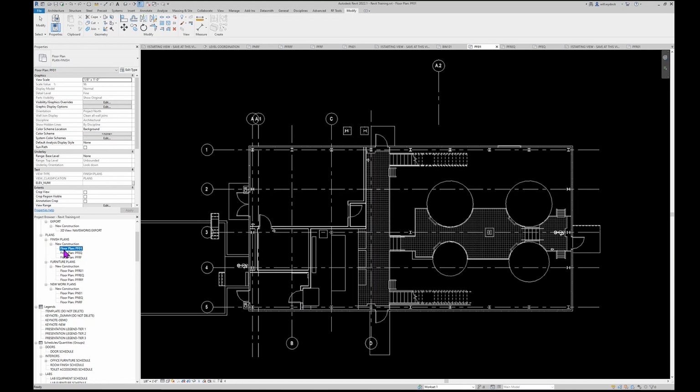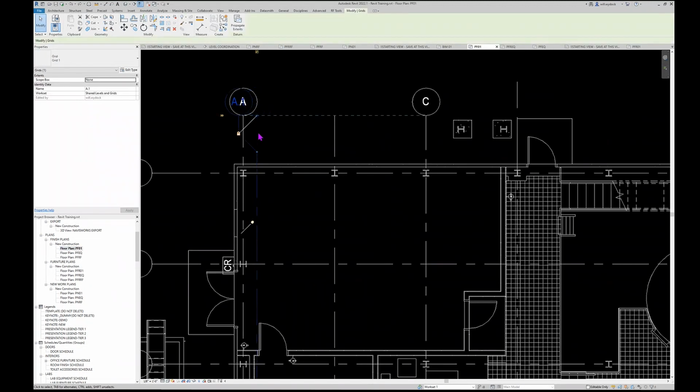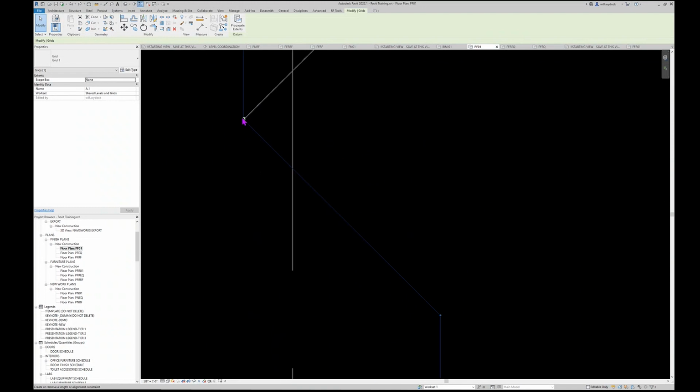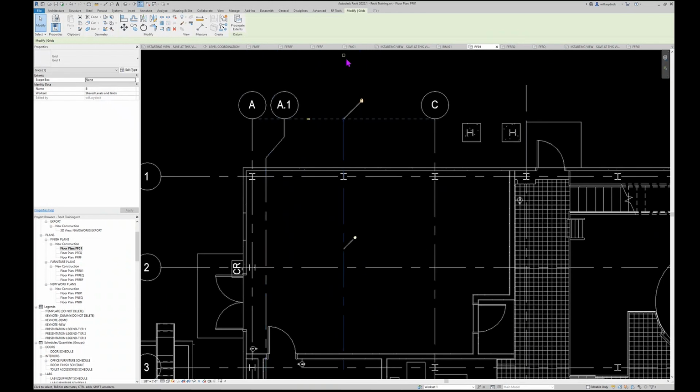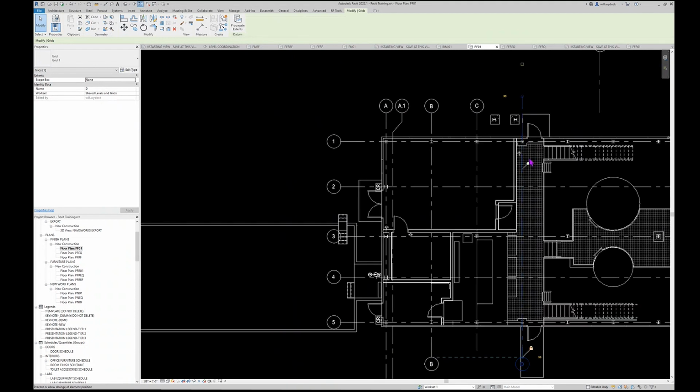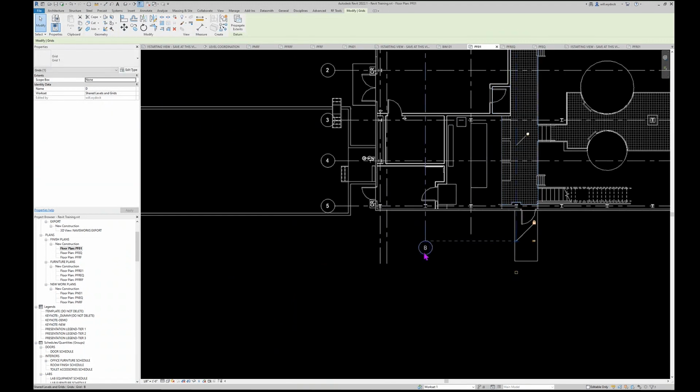There is one way to fix this type of problem where the grid heads are not consistent and graphics are not aligned. It's called propagate extents. Propagate extents allows you to pick elements in a 2D variation of them. Pick your views so that they can look nice. In this case, I'm going to have them all line up with each other. This side's going to be switched, all of these here. Have them all lined up. I'm going to uncheck this side.